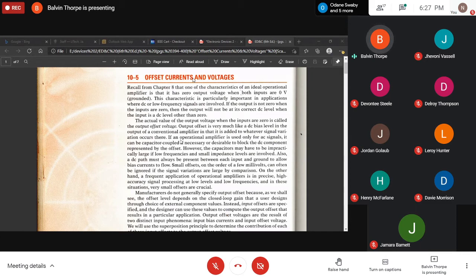And if you're going through two or three stages, at the end of the day, what you have is a false sense of security, because you have offset voltages for each stage, which are going to be amplified and outputted, giving you a false output voltage as compared to what is expected, which can, of course, throw things off. So it means that we're going to have to look at ways and means of how we can actually account for these voltages, all right?